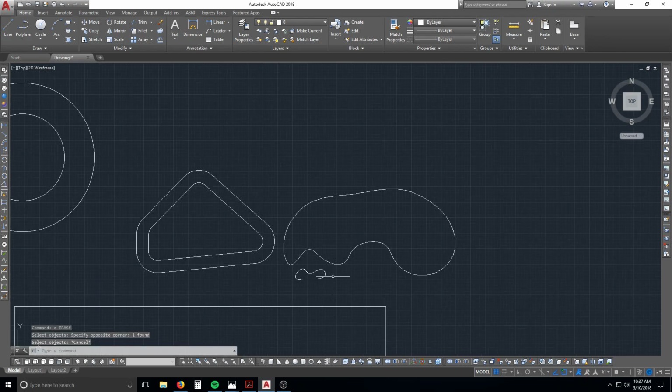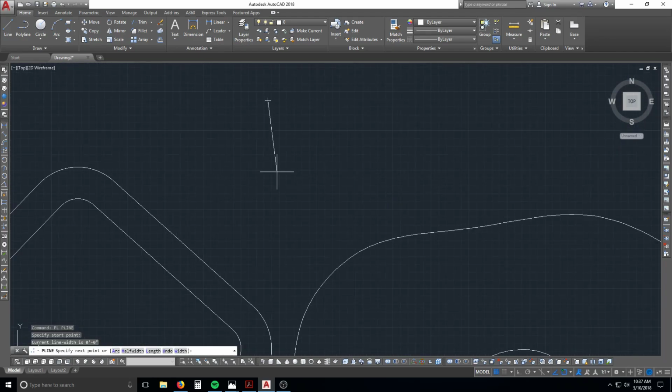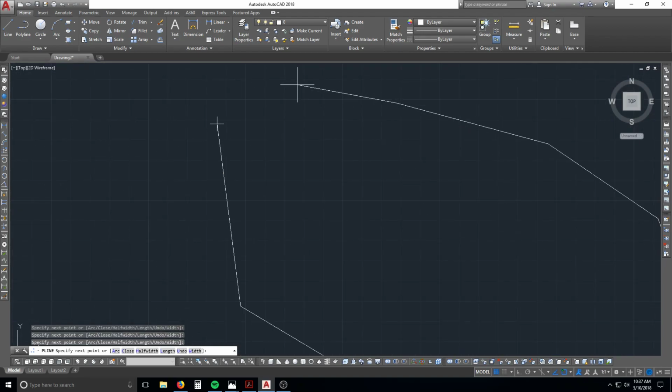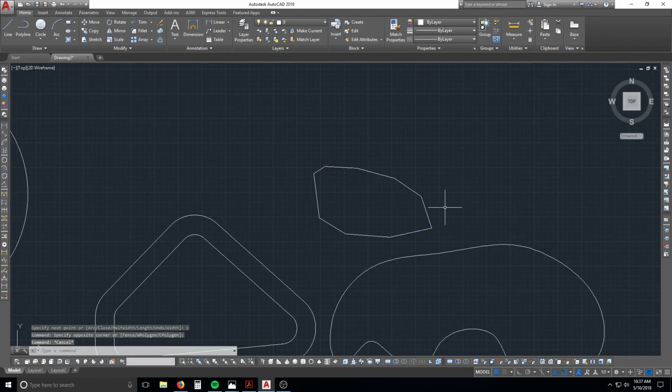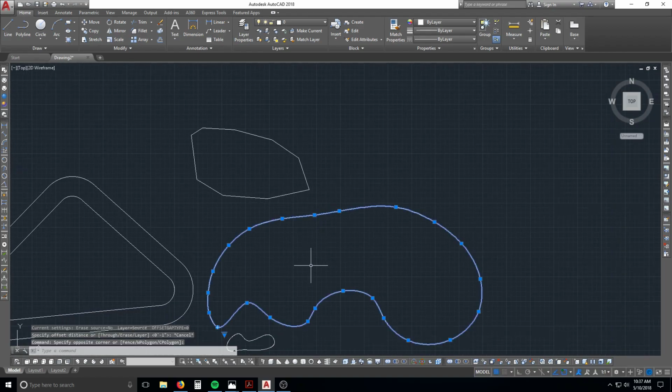And now that we're talking about things that I've forgotten, there's another one, polyline. I've mentioned this several times. PL, enter. That was a left click and a left click here, left click. Now, instead of coming all the way over to this, even down here, you can type in C for close, and it's all one line. And again, because they're polylines, you can offset it.